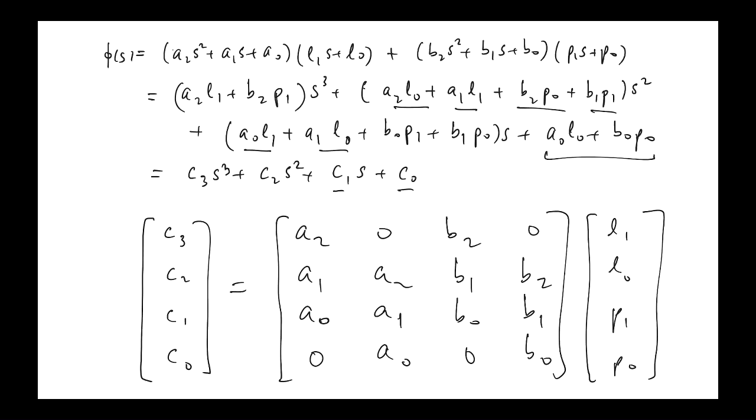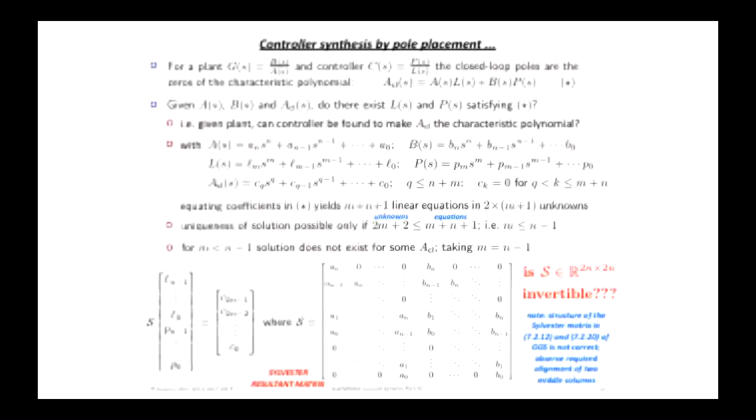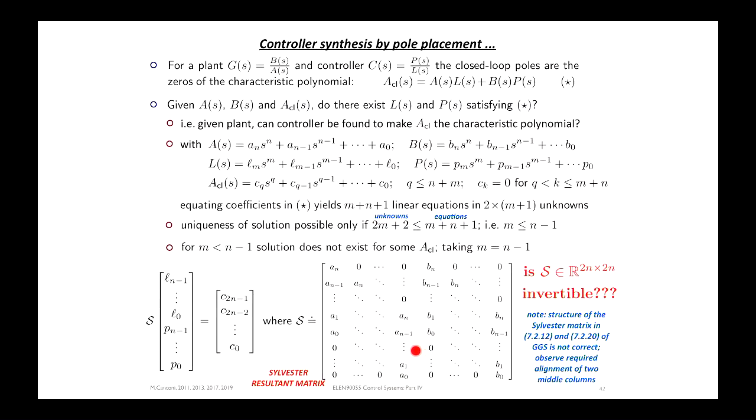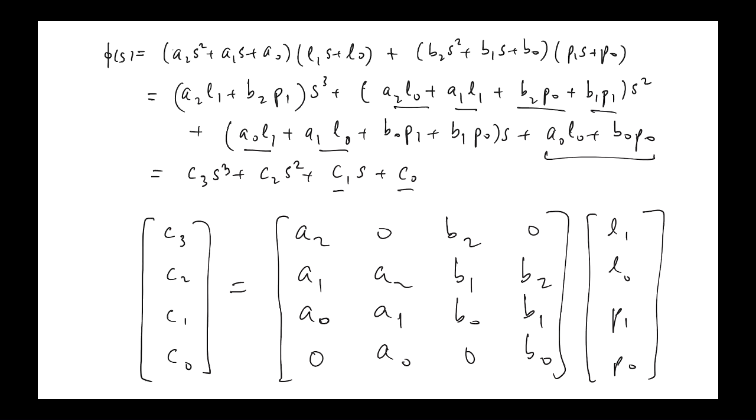And then move to the next column, we put a 0 at the top, and again, list the coefficients down. And that's the pattern that's being drawn here for higher order polynomials. So you write down all the coefficients of the A polynomial, then you put a 0 and write them down again, put a 0, write them down again, so you get things across these diagonal lines matching up in the way shown here.